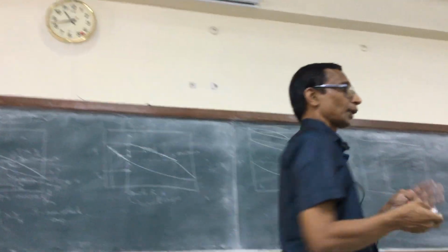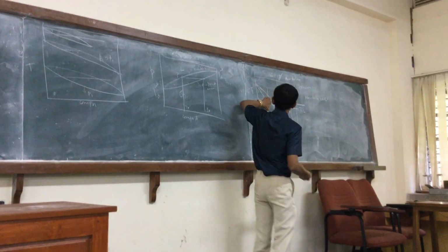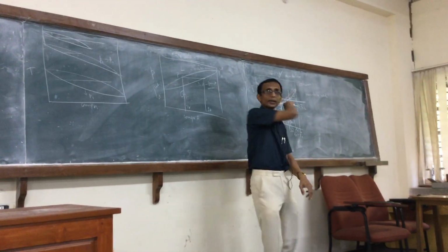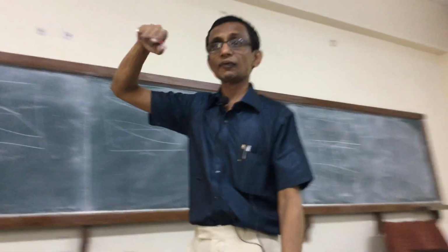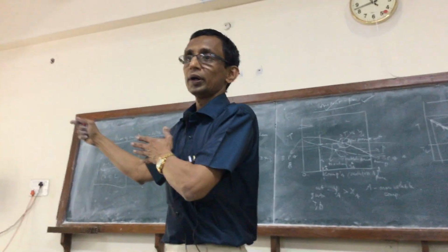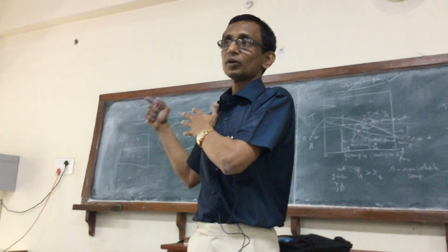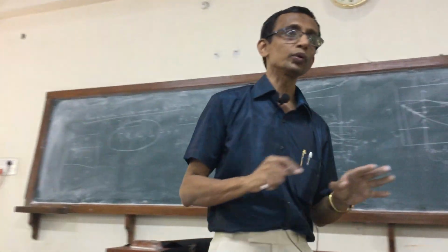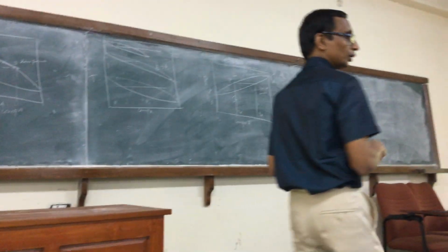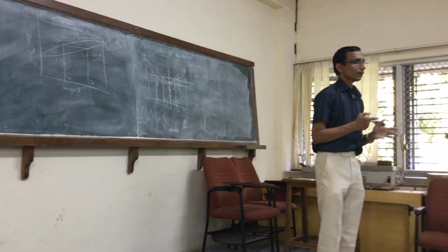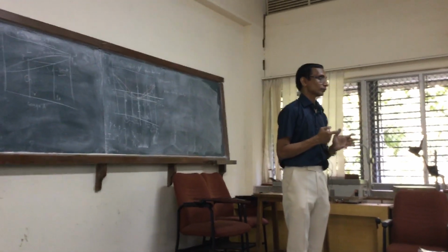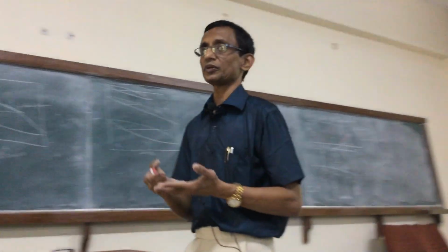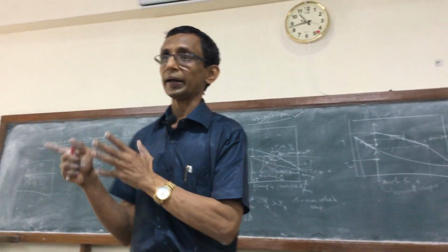So I have chosen pressure and temperature, but the state is not fixed, because I see one set of liquid-vapor in coexistence. There is another also, because the constant temperature line intersects the envelope at actually 4 points. That means 2 distinct vapor-liquid states are there. So the phase rule has to be interpreted very carefully, because when you just count the number of equations and unknowns, you need not always get a clear-cut answer, because you might have seen even for linear equations, the number of equations equals the number of unknowns. That is the whole idea of the degree of freedom.